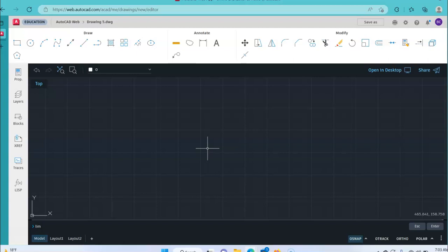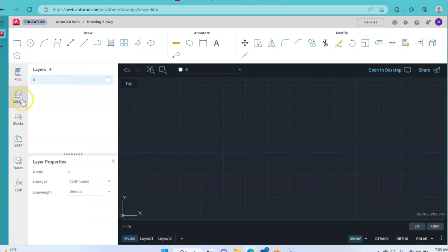And we'll talk more about that later and why it is important to have limits set on your drawing. So the next step again, we do our units, then we do limits, and now we're going to create our layers. So here is my layers properties manager.